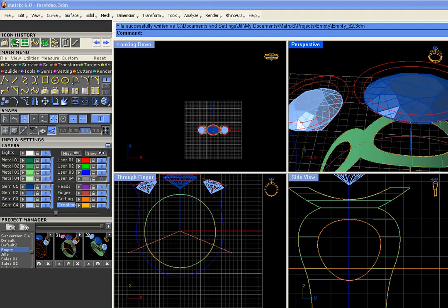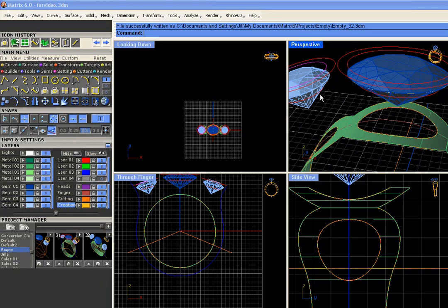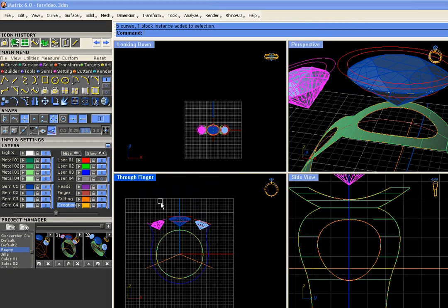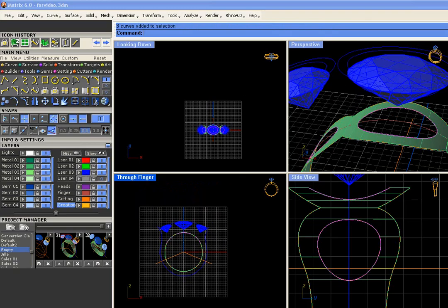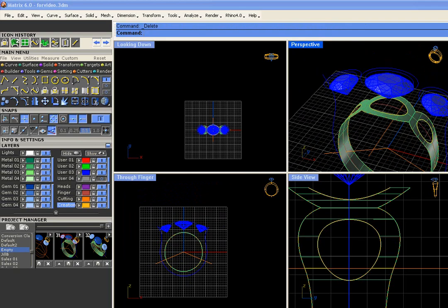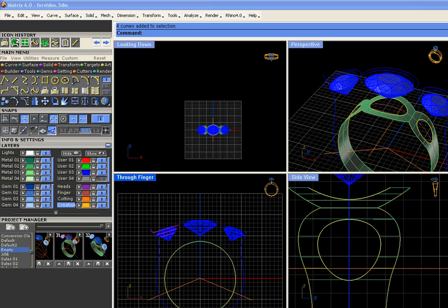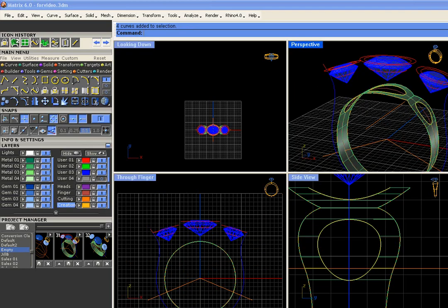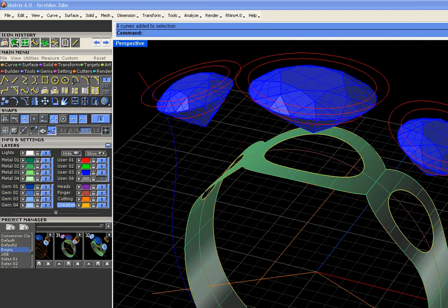So let's grab all the good red curves. Good. Oops, shift. Good. Yeah, there's a better way to do that. Stick them on another layer color and grab all the bad red curves that we know are bad, those three, and delete them. Okay. And now we're ready to loft to create these bezels. We're going to loft with the hole at the finger rail.